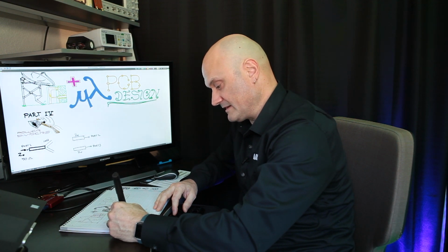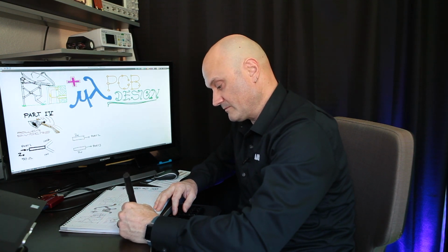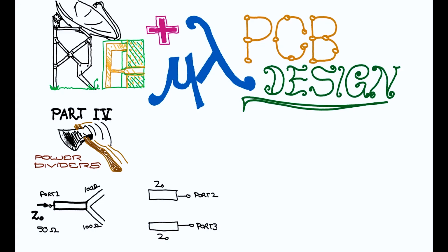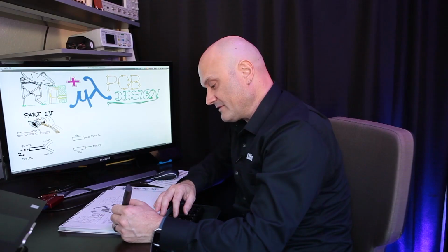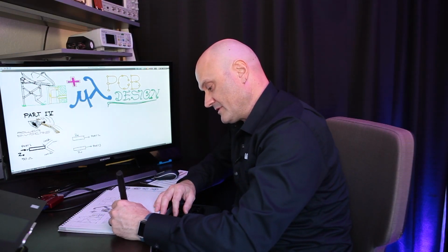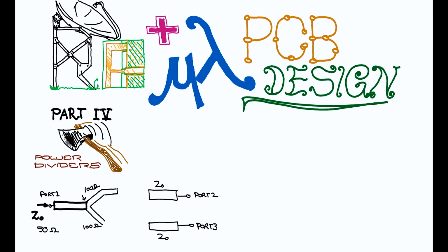This is just theoretically, say, for all intents and purposes. And then we have a perfectly matched junction here. And so where it's matched, there's not going to be any reflections or anything like that, assuming it's designed properly. And then we have this other issue where we have 100 ohm segments, 100 ohm transmission lines, and now those are no longer matched to our 50 ohm output ports.